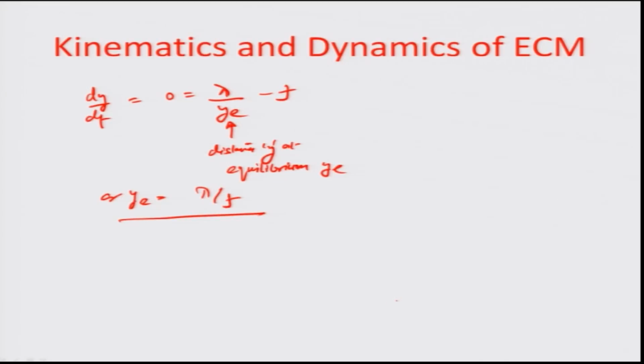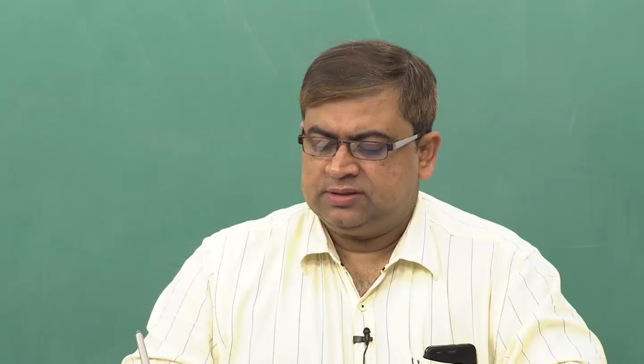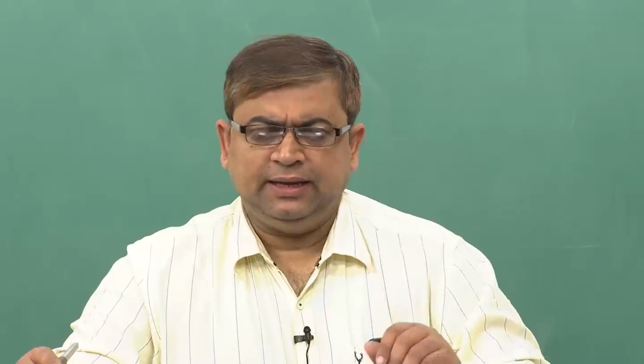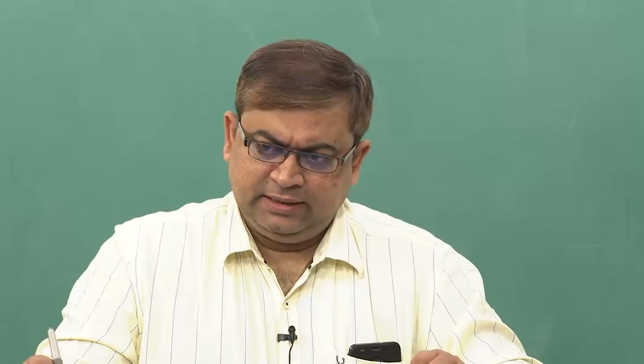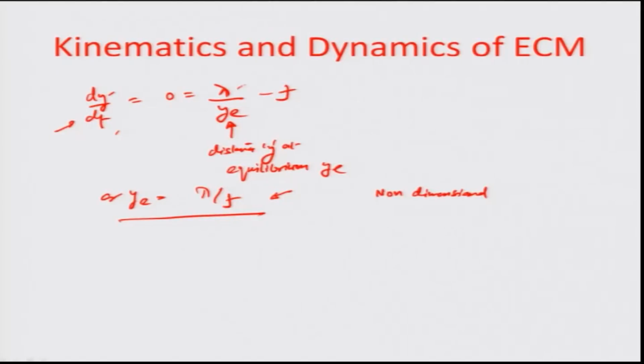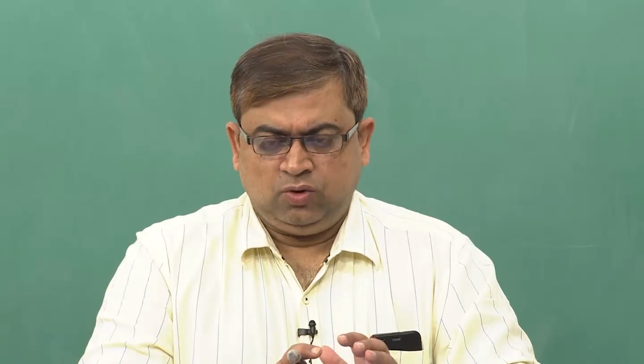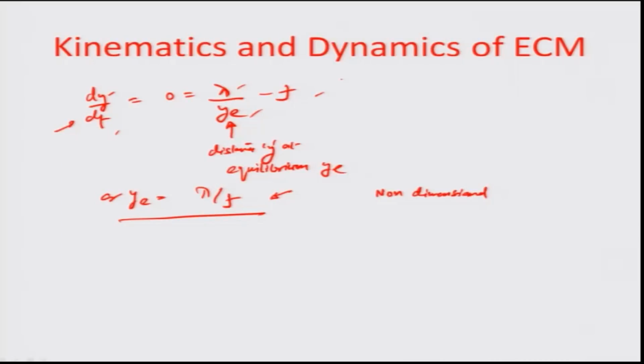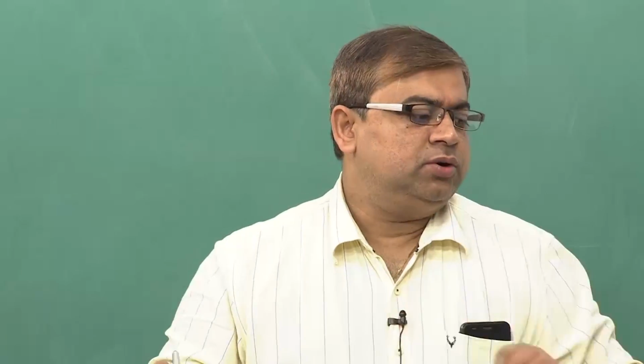Okay. So, let us now change gears a little bit and try to see how to make this scale independent. We want to make this equation non-dimensional or scale independent, because typically the IEG, the inter-electrode gap, is very small, and if you were to computationally try to predict the various values in the equations given here, there is a possibility that a numerical term may dominate and spoil the whole process of estimation. So, therefore, it is important that we get a scale factor, and then try to solve everything in terms of a ratio. Okay. So, here also we are doing this.